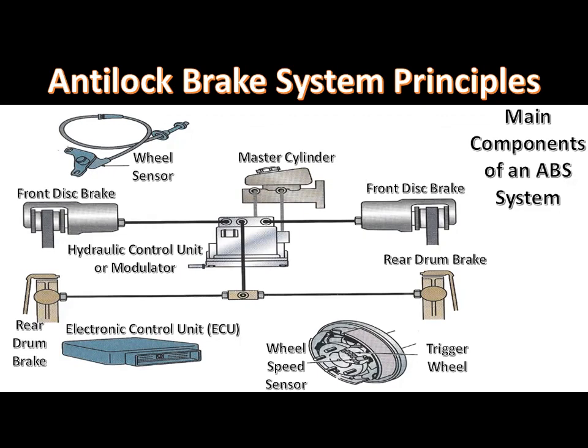This action provides tire traction while braking, and stopping distance may be reduced depending on the road surface and other variables. Cornering tire traction also decreases significantly if the wheel locks up during the brake application. Wheel lockup and reduced cornering traction during a brake application may result in loss of steering stability and control.